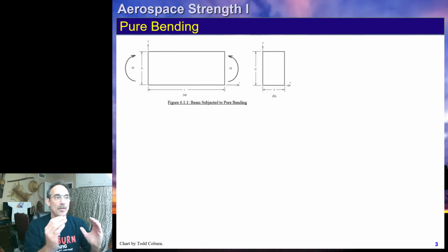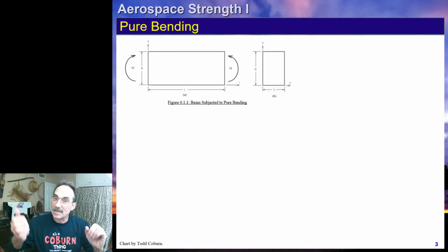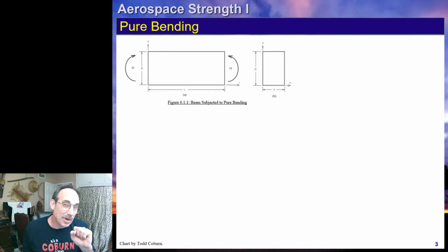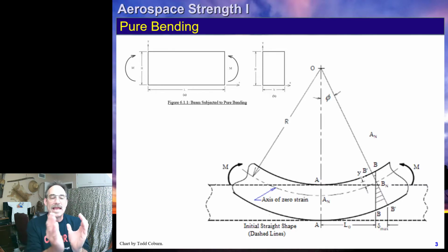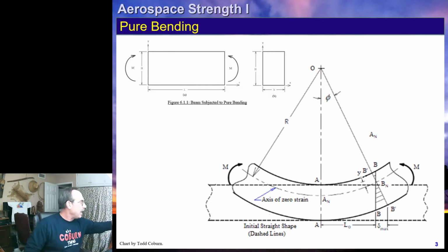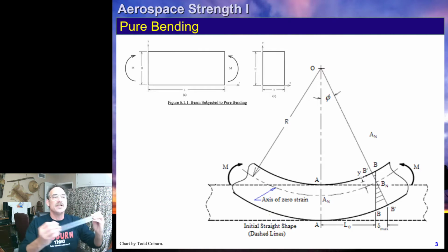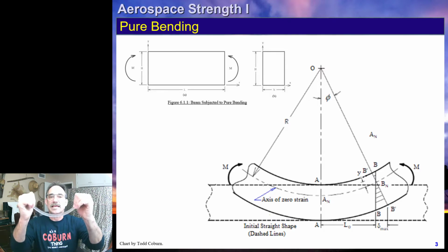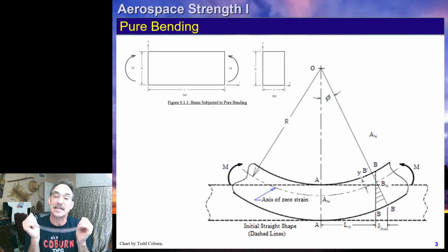So we've got this bending moment. We can imagine we're going to get stresses going from a positive value at the bottom to a negative value at the top. As we do apply this bending moment, we're going to end up bending this beam. You can see that this beam gets bent into a curved surface. For example, do I have a nice little flexible? Here we go. So if we bend this with a bending moment like this, you can see it's bending into smiley face bending. That's a common terminology when we're doing bending analysis. You'll notice as we bend it, there's a deflection of the beam. We've got a bending moment applied.